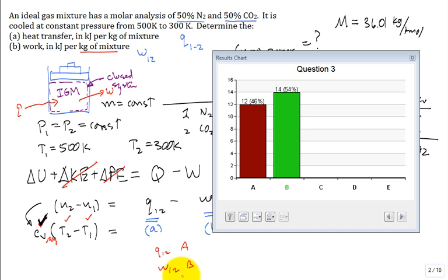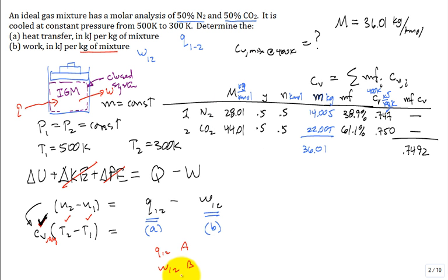Okay, for those, I'll take a brave soul. Those that voted for the heat transfer, what do you think you would do to get it? Second law, it's going to be a little tough, right? Because in the second law, you're going to have that entropy transfer with heat transfer. You do have heat transfer, and the temperature of the system is changing as you're transferring the heat. We have it in the second law, integral del Q divided by T of our system, and that T is changing. It's not trivial. So maybe that's helpful to think about, but it's going to run into a dead end.